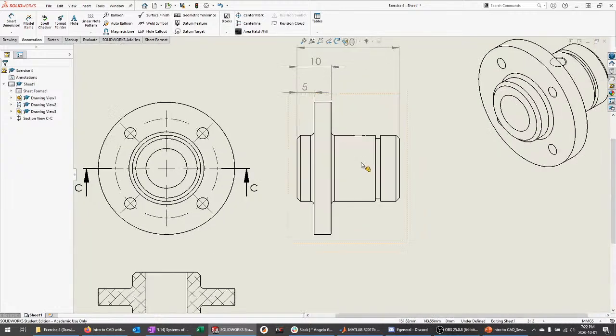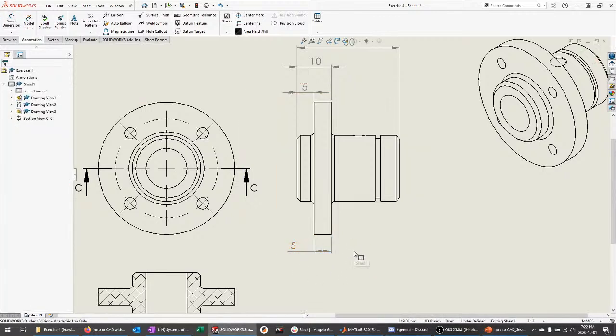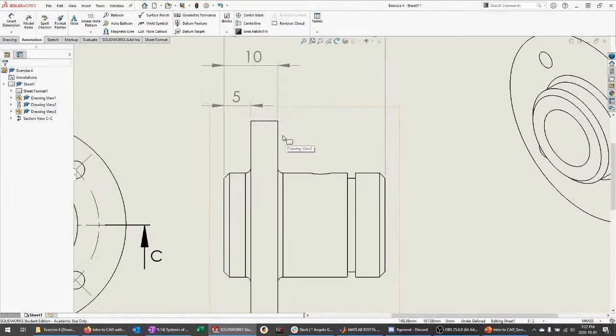This is just annotating. It doesn't hurt to have some additional information. It's better to err on the side of having more dimensions than you actually need than having fewer. Because particularly if you create a drawing to go to the ME machine shop and you realize you accidentally missed a few dimensions that are actually important information that you need, that is a bad thing. But having more dimensions than is strictly required to fully define the part is not a particularly big deal.